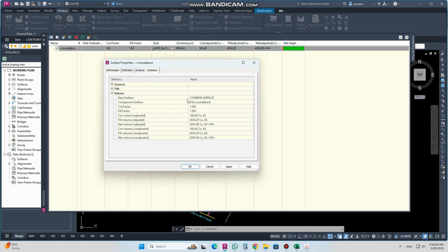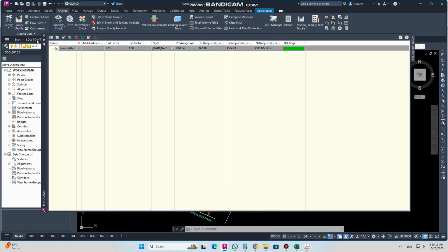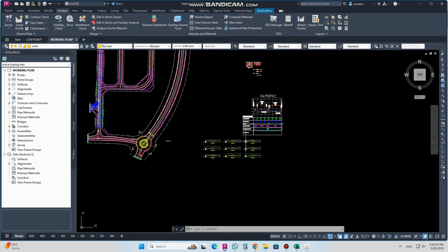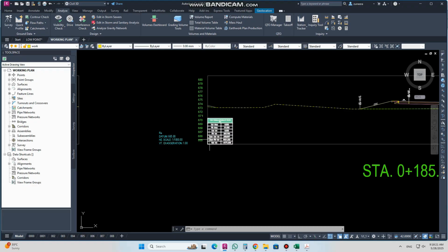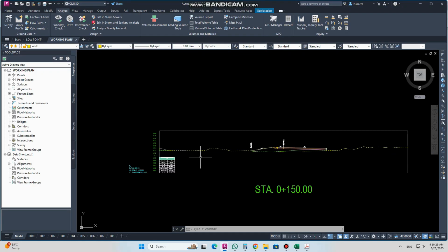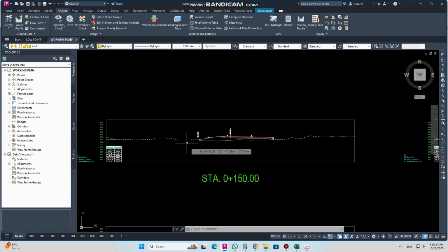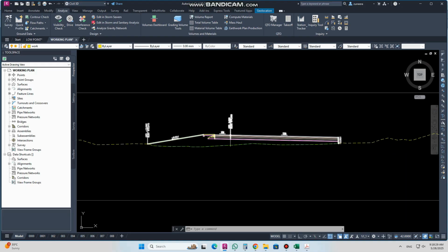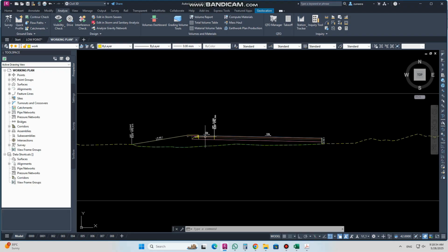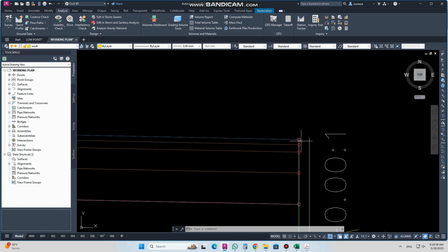The cross section is missing some places because, as you know, there are two types: the average area calculation and the zero line. In the two surfaces we calculated on the zero line. In the cross section we calculated on the average area. That's why in the cross section the volume shows less than from the two surfaces. If you face a problem here, this will be the reason.